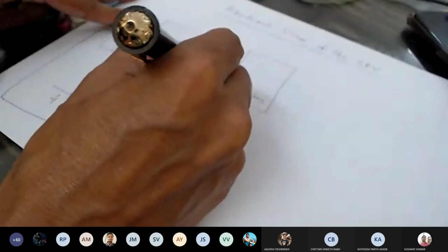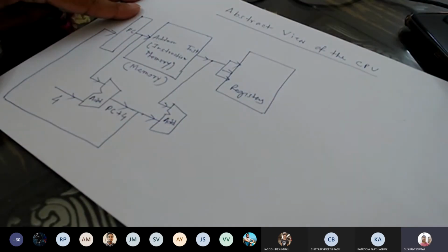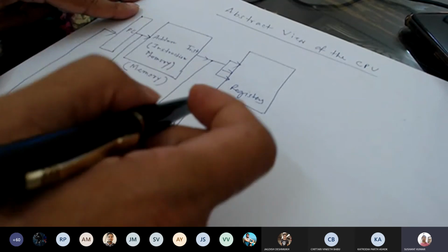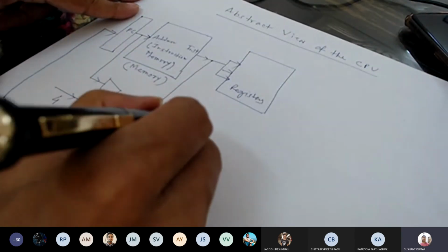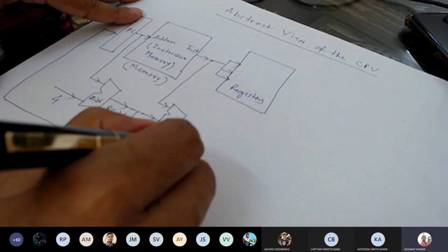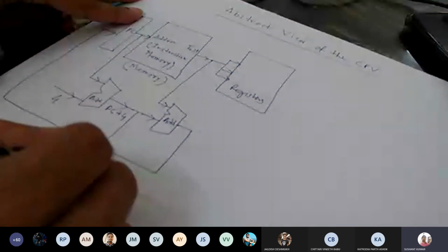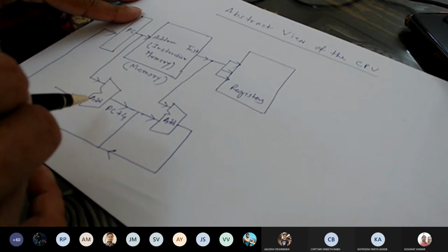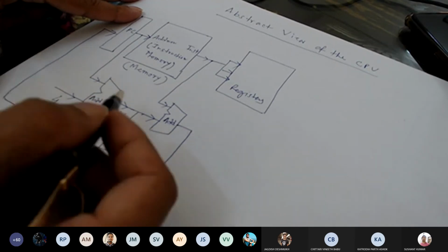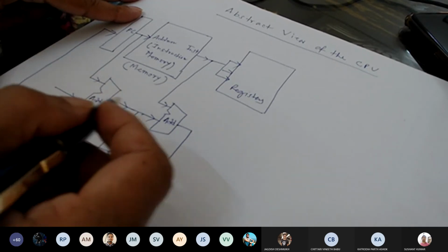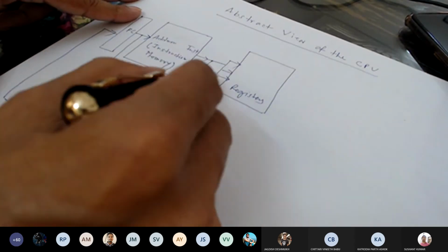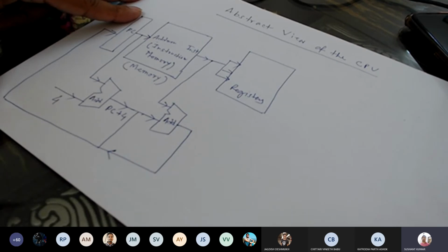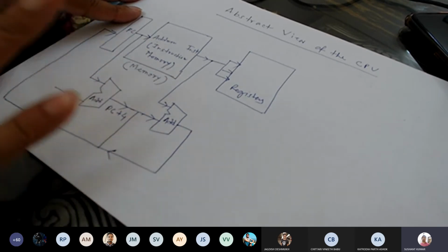Here also. Sir, but they first need to be decoded, right? No. Why does it need to be decoded? It will automatically come. First we need to separate that this is a branch instruction and where we should branch. I know that, but these are adder circuits. Okay, these adder circuits will be activated if needed. If the branch is not needed, then this circuit will not be activated, only this will work. Okay, I got it. That's why it will not always be active.